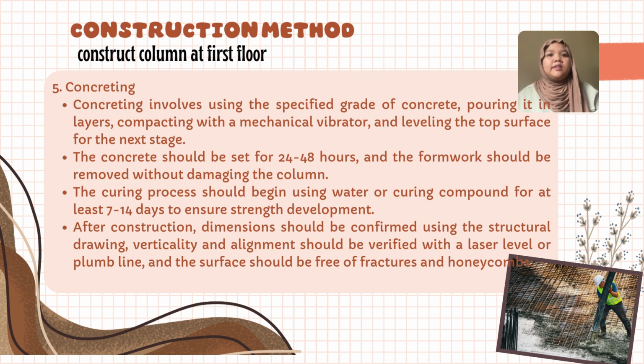column. The curing process should be using water or wet compost for at least 7 to 14 days to ensure strength development. After construction, dimensions should be confirmed using the structural drawing. Verticality and alignment should be verified with a laser level or plumb line, and the surface should be free of fractures and honeycombs.